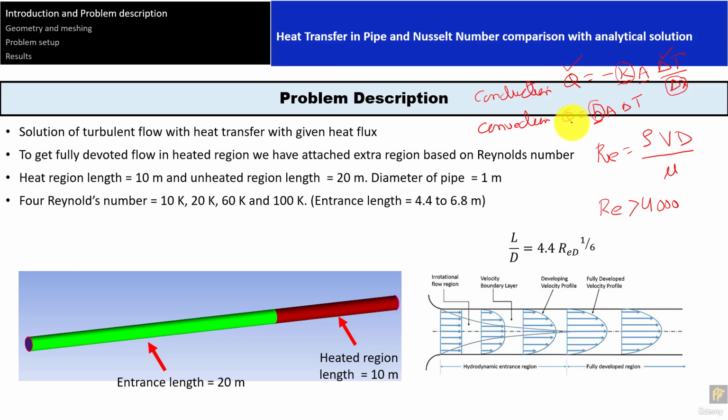This is very important because if there is a combination of conduction and convection, we can find out the value of heat transfer rate from the conduction, because in the steady state the heat transfer rate should be equal. And we know the wetted area, and also we know the delta T. This is also a question, how to find out this delta T, which is also a topic of this whole exercise. So the most important thing is to find out the convection heat transfer coefficient.